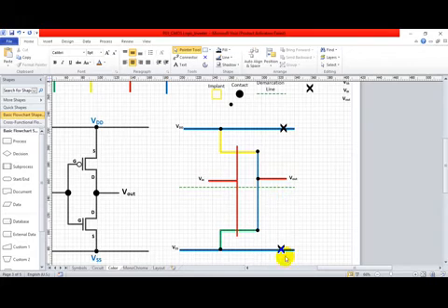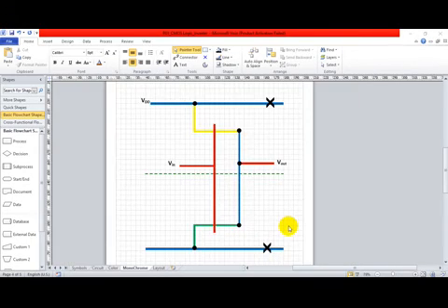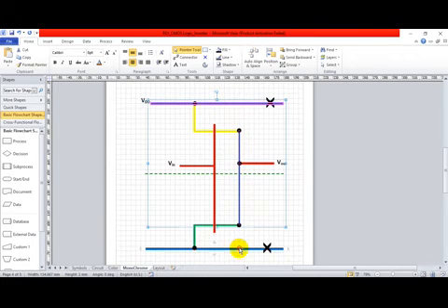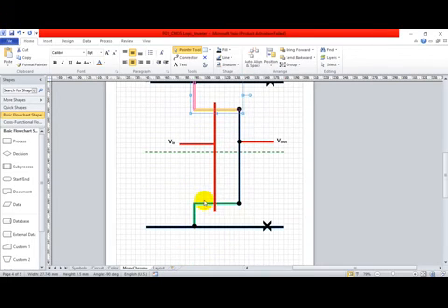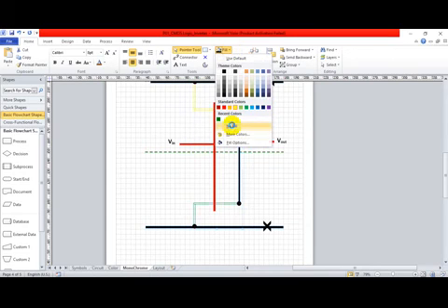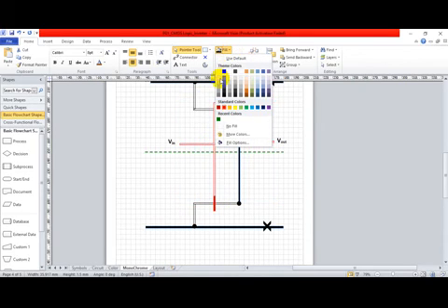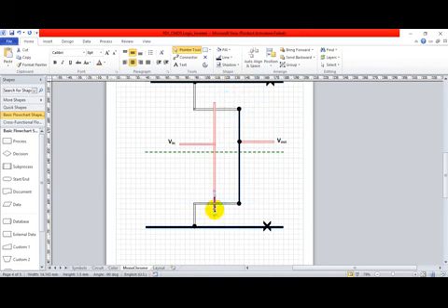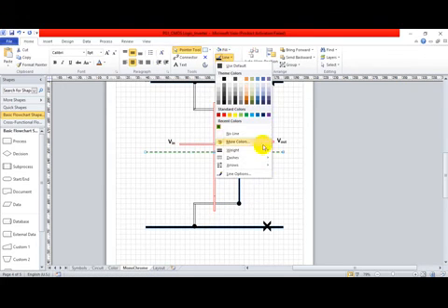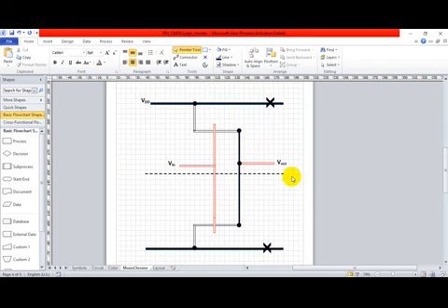The same you can have in the monochrome. So in the monochrome, how will you show it? You can refer to the encoding. The metals are represented by black color. So I will fill this with black. Whereas your diffusions are empty rectangular boxes, so you change it to empty rectangular boxes like this. Poly is represented by some black color filling, so as of now we'll fill with this. Same here. The demarcation line is also black. This is the monochrome encoding layout.